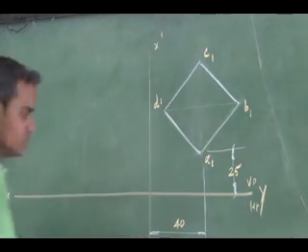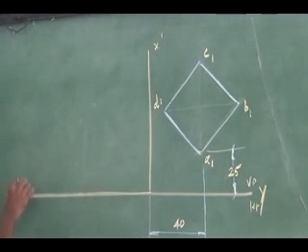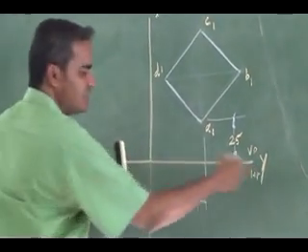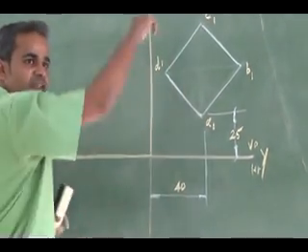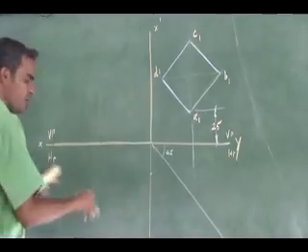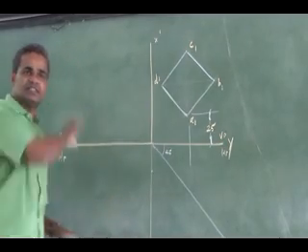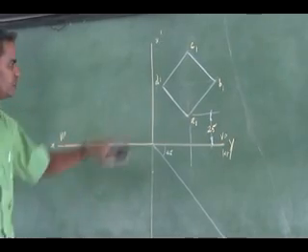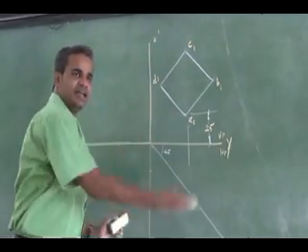If I open this, with reference to this is my vertical plane, this is my horizontal plane. So I am opening it, closing it. With a 45 degree line, this top view and the side view will be linked. With the 45 degree line, the top view details and the side view details are linked. Similarly, the front view and side view details are linked. It is in line horizontally. Front view and top view are in line vertically. Side view and top view are linked with a 45 degree line.